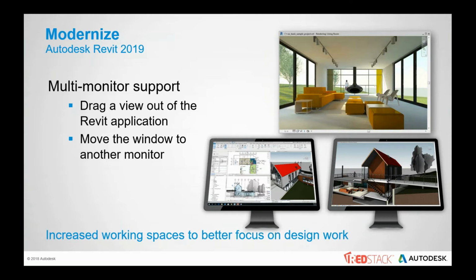Multi-monitor support is one thing that everyone has asked for. So if you're using Revit and you have more than one display attached to your system, Revit now provides full support for use on multiple monitors. You can drag a project view out of the Revit application window into its own window, and then you can move that window to another monitor as needed to support your workflow.